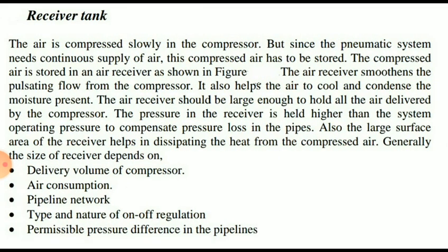Then the next element is the receiver tank. It is the next element after the compressor. The air is compressed slowly in a compressor. But since the pneumatic system needs a continuous supply of air, this compressed air has to be stored. The compressed air is stored in an air receiver, that is shown in the next slide. There is a diagram in the next slide. The air receiver smoothens the pulsating flow from the compressor.